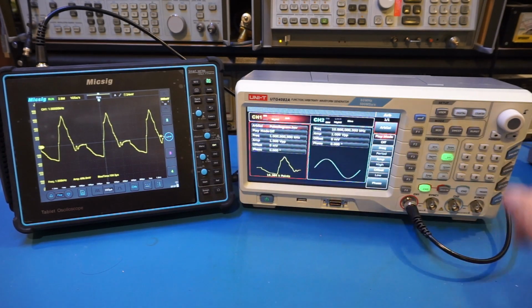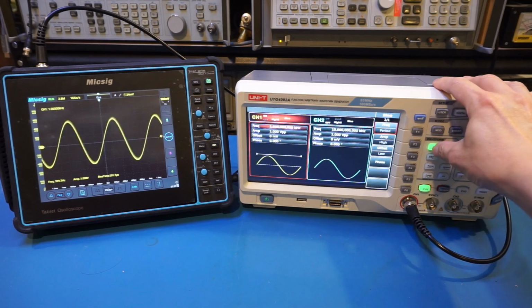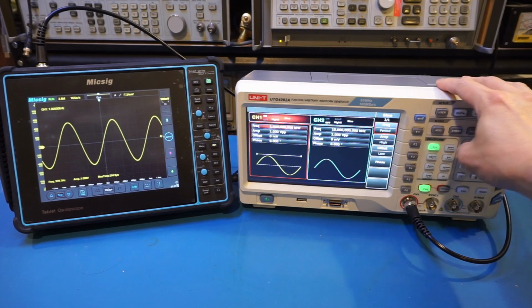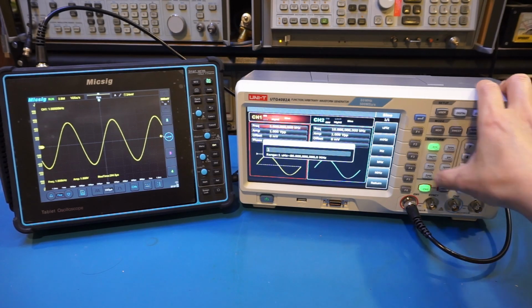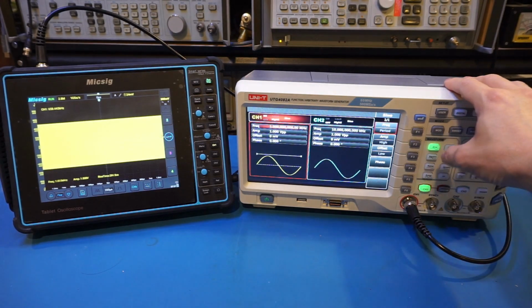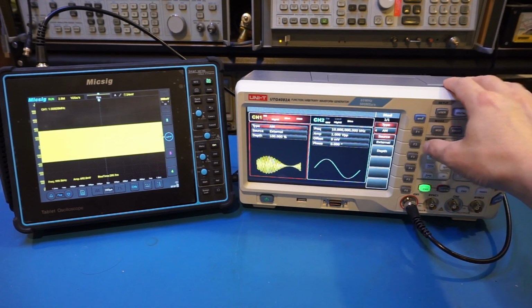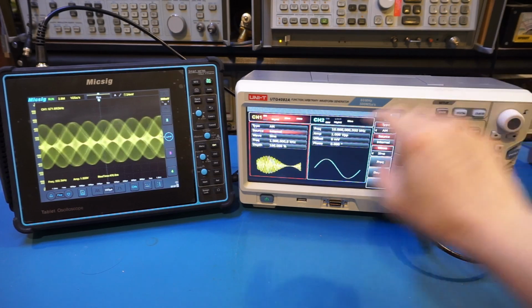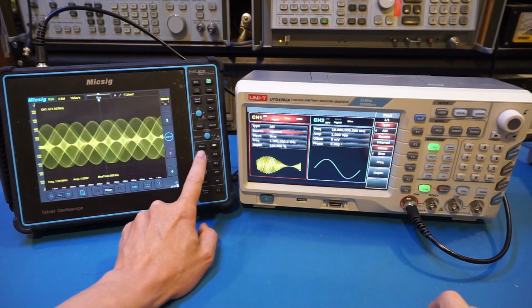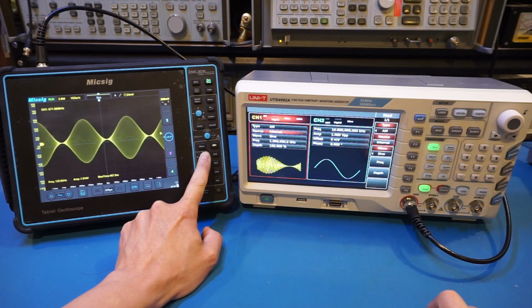We'll demonstrate a few. So let's go back to sinusoidal here. This is 1 kilohertz. Let's do a carrier frequency of 1 megahertz, so that would be easier here. And let's do modulation. That's external. Let's first change it to internal. We'll take a look at external a little bit later. So right now we're modulating a 1 kilohertz signal on top of the carrier.